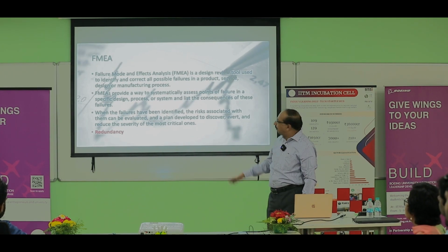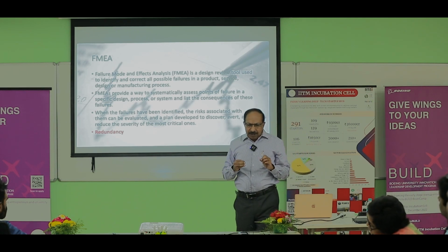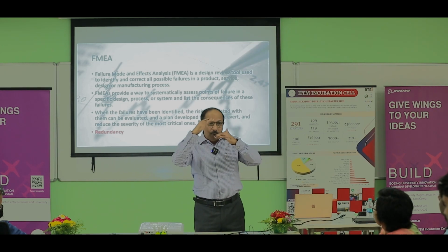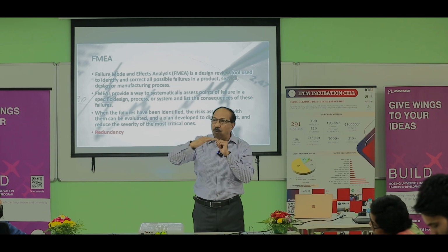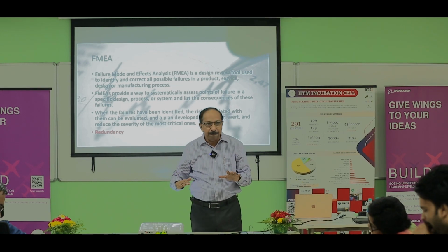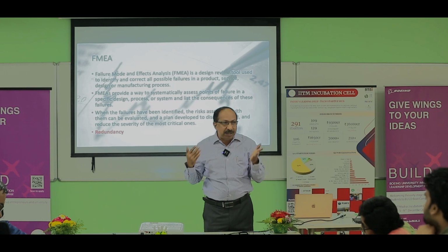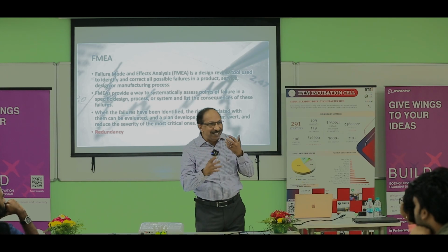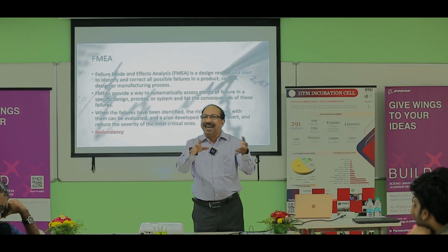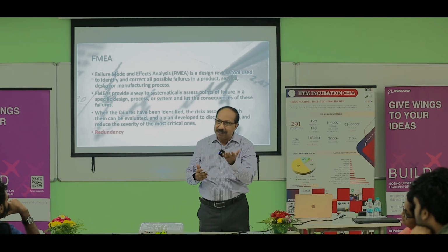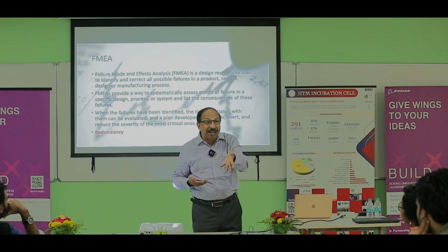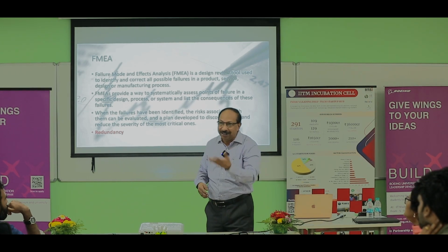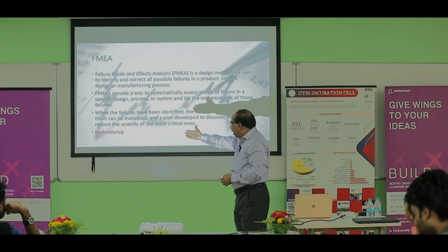I will rush. FMEA, failure mode. See, there is no product which will not have any failure mode. There can be many failure modes. You have to imagine and list down all the possible failure modes. Once you identify a failure mode, the first thing to do is take care of that risk, maybe by changing something. For example, in a healthcare product, you have to make very smooth surfaces, not sharp, smooth curves and all. It should not hit the patient and injure them. And redundancy.